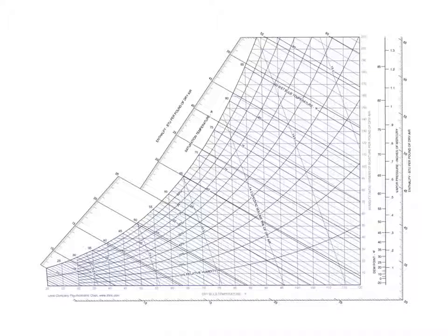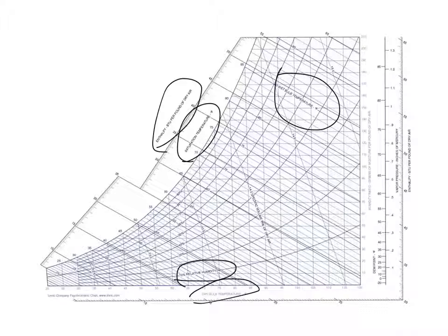So I'm not even going to try to draw a psychrometric chart. The chart looks like this. If you haven't used a psychrometric chart before, it looks like there's a lot going on. Looking at the chart, you see dry bulb temperature, wet bulb temperature, saturation temperature and enthalpy, relative humidity, and several others. The cool thing about a psychrometric chart is that if you just know two of these properties, you can tell a whole lot about the state of the air that you're charting. Let's move this out of the way and then break it down into its components.